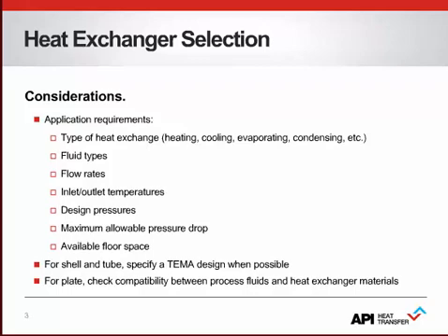Temperatures and pressures are, of course, important factors when deciding on a design. These variables directly impact key design attributes such as material selection and mechanical design details, such as thickness and quality testing requirements. Pressure drop is always a concern when designing a given type of heat exchanger. There are select designs that are better suited for accommodating lower pressure losses at the expense of lower heat transfer efficiency when that trade-off is warranted. Footprint is an important factor as well in the heat exchanger selection. It has become even more prominent in today's world where every inch or centimeter of space needs to be used as efficiently as possible. So we will discuss compact options for heat exchanger design later today as well.